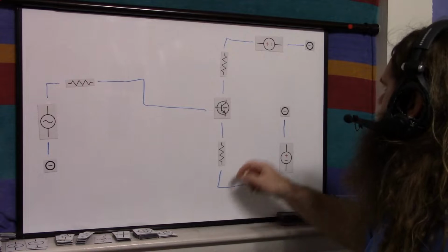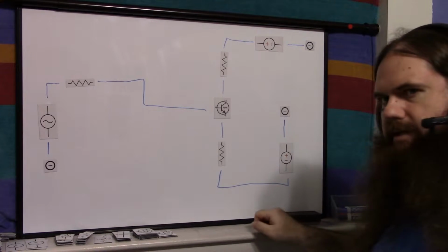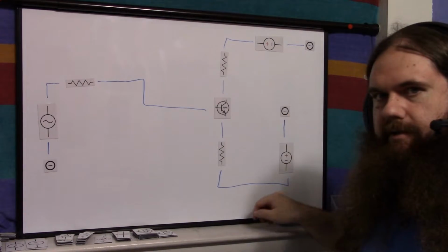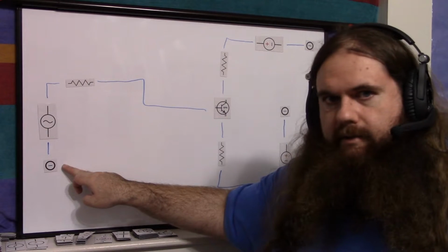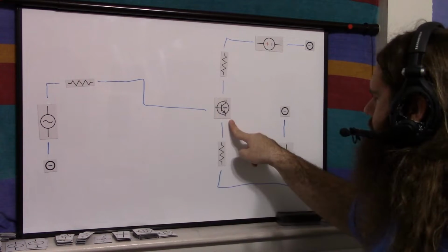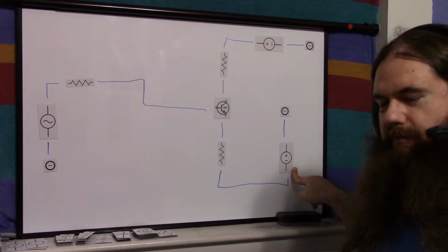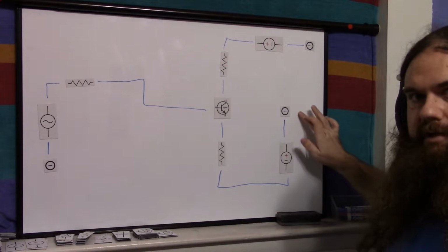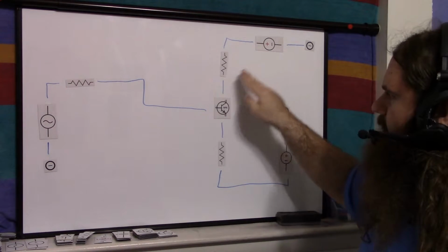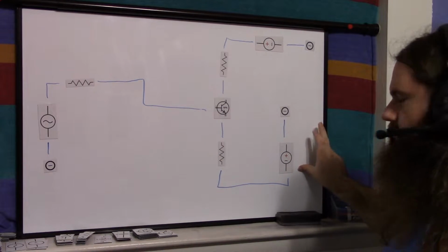It works. Because you look here, you say, okay, well, if you look at the positive end here and it goes through here, but then it's connected to the negative end, but then it continues. They're in series. These two are in series. So when this signal is at the reference voltage, the base is at the reference voltage, the emitter resistor is connected to the lowest part of the circuit, which is this much voltage below the reference voltage. If this is 5 volts, this might be 0 volts, this might be negative 5 volts. So this would be 0, this would be negative 5.